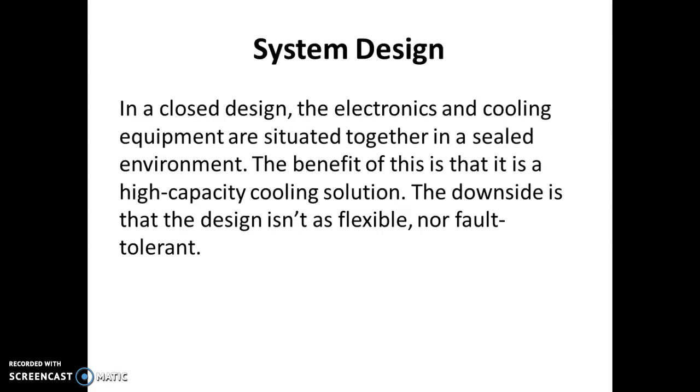The fourth one is the economizer. Two types of economizers are there: one is the air side economizer and the second is the water side economizer. To optimize airflow, we make use of three techniques. One is hot air versus cool air, the second is raised floor, and the third is vapor sealing, that is the vapor barrier. A plastic or foil sheet can be used as a vapor barrier.